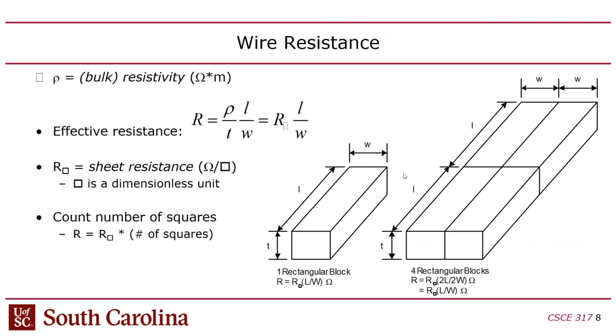Well, silicon forms the bottom part of the chip, the substrate and the diffusion areas and the wells. Those are called the active layers, so that's at the bottom. But then you have layers on top of that. You have layers of metal that are separated by oxide that isolates each layer.